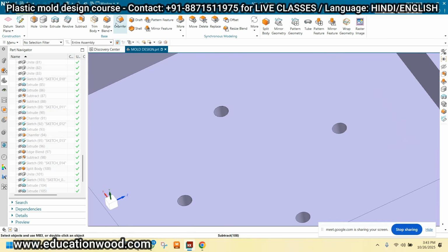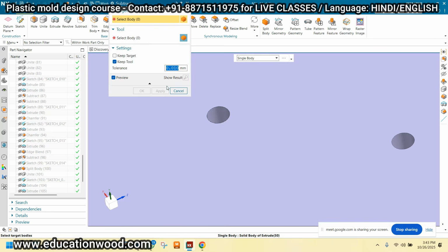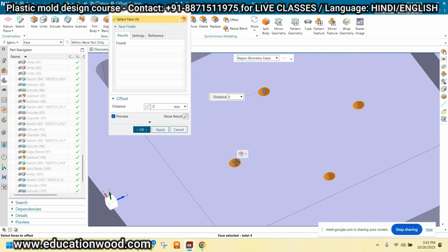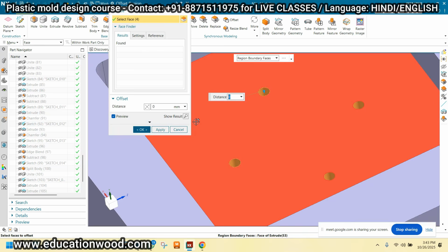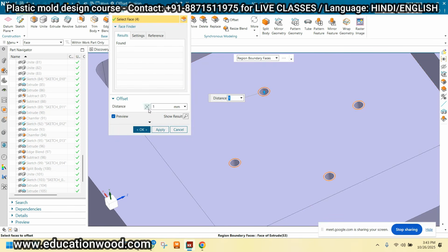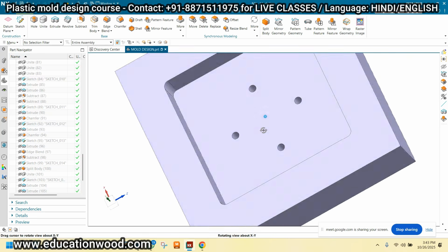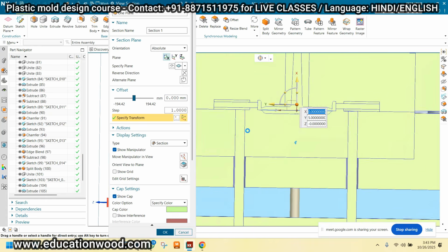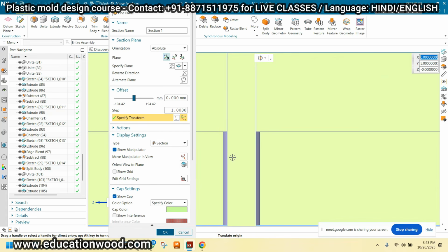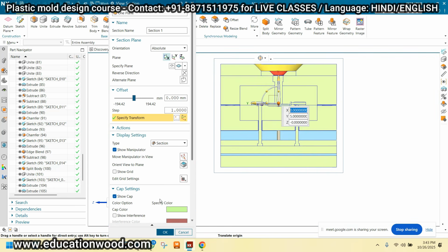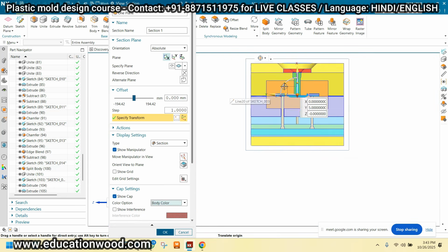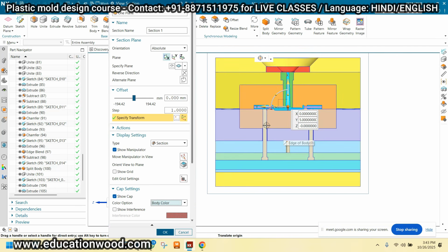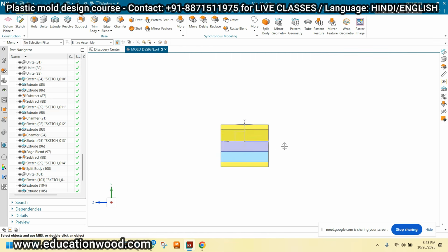So we should provide the clearance here because we do not need a precise dimension here, because we have an insert. So I can take 1 mm per side. See, right? So it will look like this. Control J. See, understood? This understanding is very important. So this is the single cavity. Oh, sorry, the four cavity slider mold right now. So we have prepared the complete mold base.